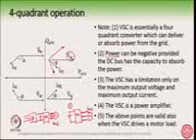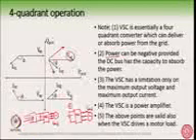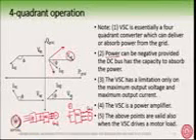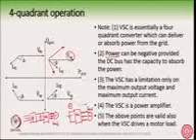Now when you say that the power is negative, what do you mean? Power is positive means power is flowing from this side to this side. Power is negative means power is flowing backward. So when the power is going backward, in case of option 2, there is no problem, because this battery up to its capacity can absorb the active power. It will be used in charging up the battery.